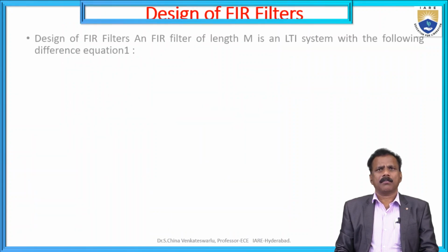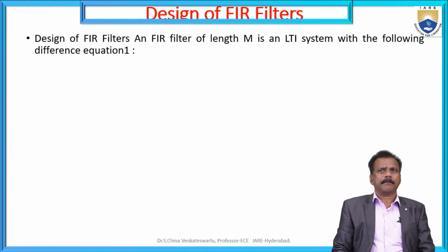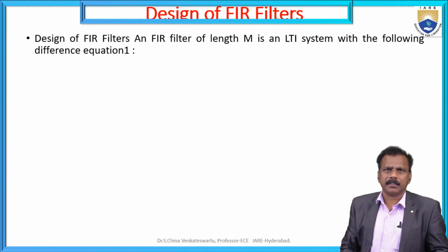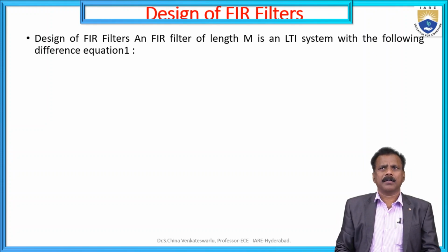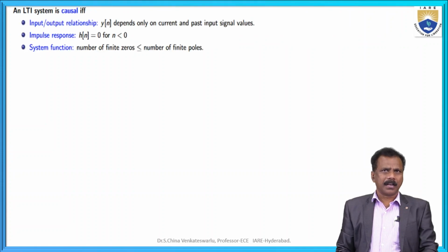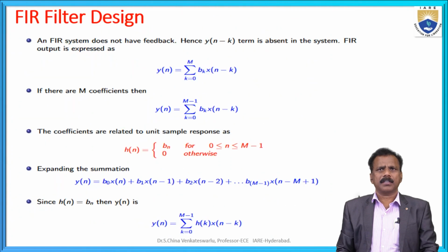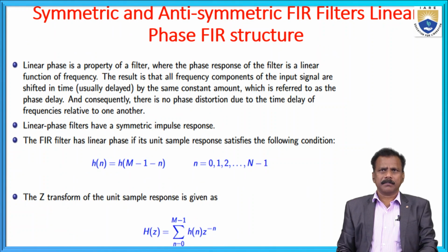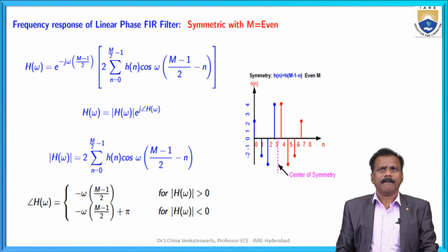Now we are to design an FIR filter of length M, an LTI system with the following difference equation. We also verified that an LTI system is causal, and we have seen the symmetric and anti-symmetric FIR filters with linear phase.